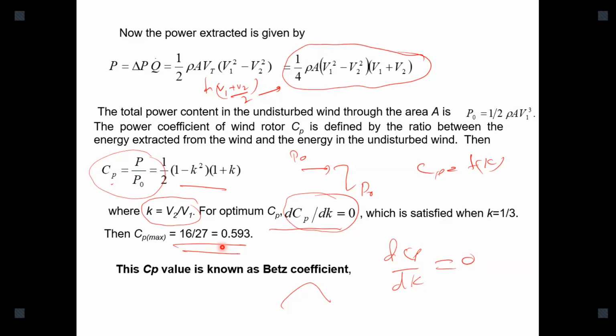That is the reason that in most commercial wind turbines, even very advanced, large wind turbines, the CP value is around 0.42, 0.43, like that. Even less than that value. Keep in mind that the conversion efficiency, the CP value, is given like that. You can check that in any values, because there are some other losses, such as wake loss. We can talk about why that wake loss happens. Okay.